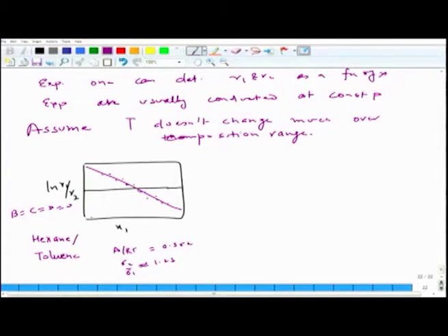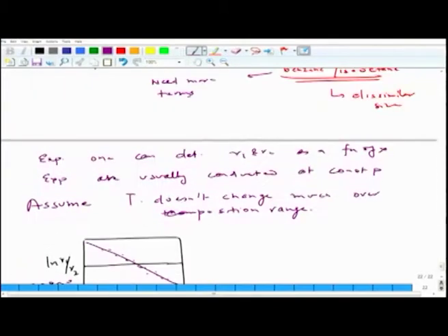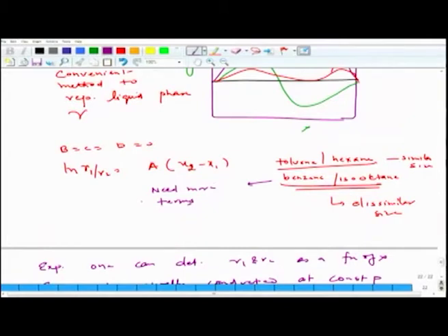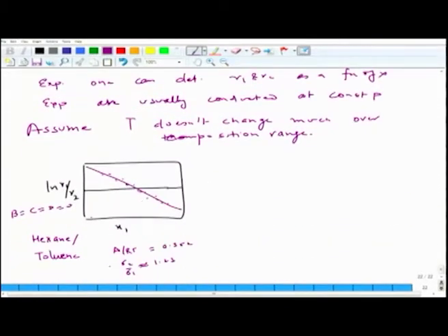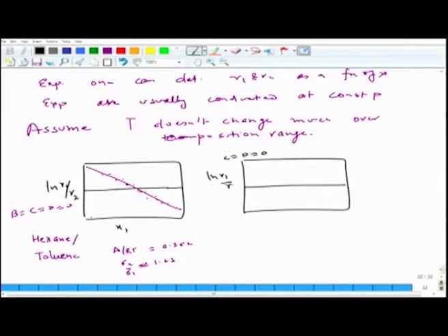Now, if you consider, as I said, benzene and isooctane, I said these are not good enough because they are dissimilar in size, as the ratio of the sigma is around 1.86. So in this case, let's look at how the data looks. Again here C is equal to D is equal to 0, so I'm going to consider B also in this case. There are two parameters, so it is something like this, and the data are pretty much well fitted.